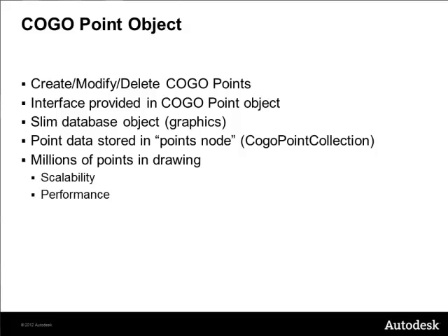Cogo Points and associated functionalities exposed in the .NET API enable us to create, update, or remove Cogo Points. For those who didn't have to deal with Cogo Points earlier, let me give you some basics. Cogo is short for coordinate geometry. Cogo Points in Civil 3D are more complex than simple AutoCAD points, which have only coordinate data. A Cogo Point object, in addition to a location, also has properties such as unique ID number, name, raw description,